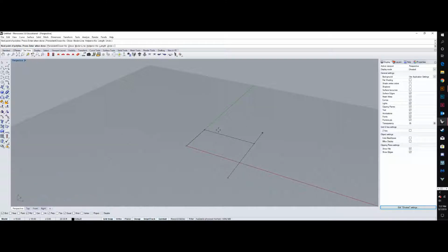Now it didn't register that that was 10 feet, so I'm going to click my little pointer tool, and notice it got rid of it all, and that's okay because it's not going to slow me down very much. So 10 feet, click, 15 feet, click, 10 feet again, click,